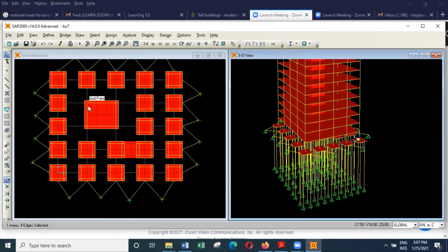Sometimes these piles may not be sufficient because some of these loads can be higher. In that case, you might need additional piles or a larger diameter pile. The problem with very large piles is when you try to maintain the center to center spacing, you will find that the 3 times rule cannot be maintained, and so some geotechnical consultants do not have a big issue with large diameter piles.